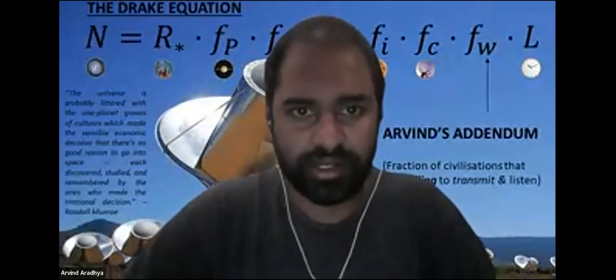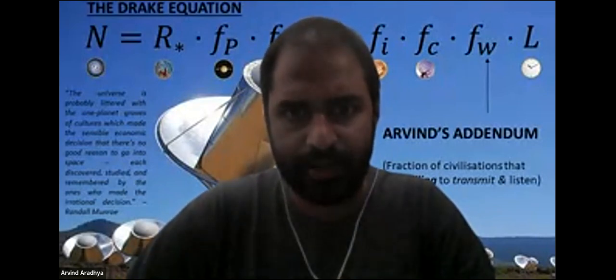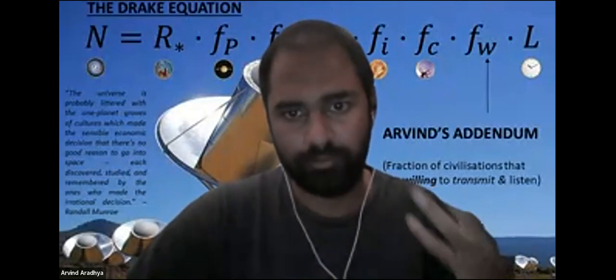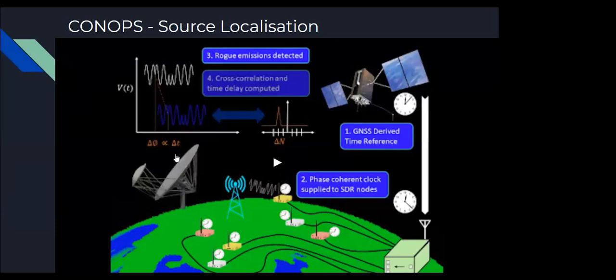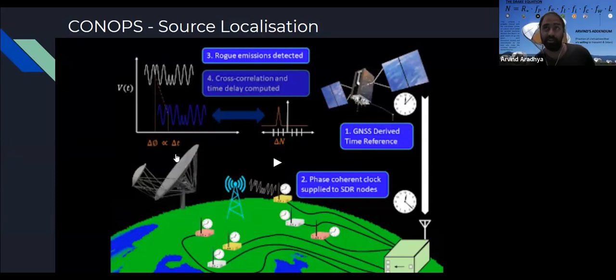In order to actually do the correlation that we're doing, time domain correlation, where we're recording the voltage waveform versus time, is a little hard to do because light is so fast. It's 300,000 kilometers per second, and that's really fast, right? So you need to have a really precise clock, which is another reason we're using the GPS derived clocks. And you need to record for a certain length of time so that you can achieve a good correlation.